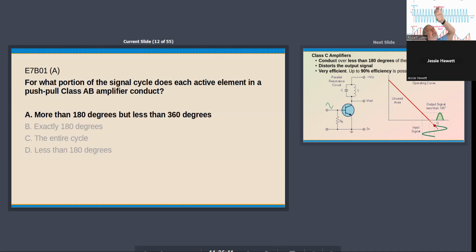So you're missing most of this cycle and most of that cycle, but right at the crossover, until it starts operating efficiently, you're losing that amplification. And all they're doing is changing the bias with those diodes, so that it conducts during the crossover. Basically, get rid of the crossover.